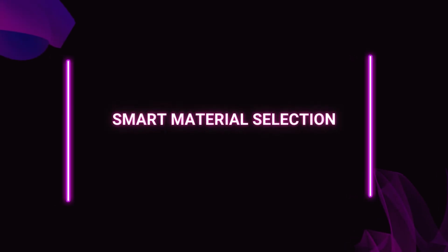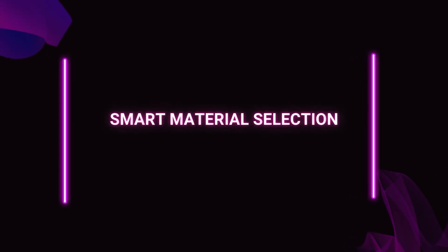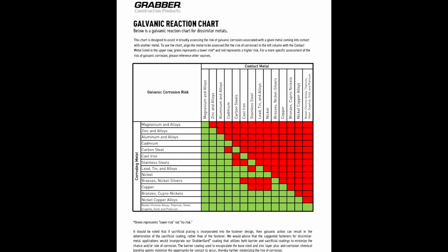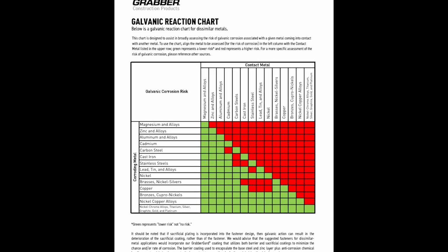Need a design with dissimilar materials? You can prevent corrosion by breaking the battery circuit, and here are 4 different strategies to keep in mind. 1. Smart material selection. Your first and best defense: refer to the galvanic series chart. The closer the two metals are, the lower the risk. Now, a good pairing using stainless steel fasteners on a 5052 aluminum enclosure is very common and generally a safe practice. While there is a potential difference, it's small enough for most operating environments.